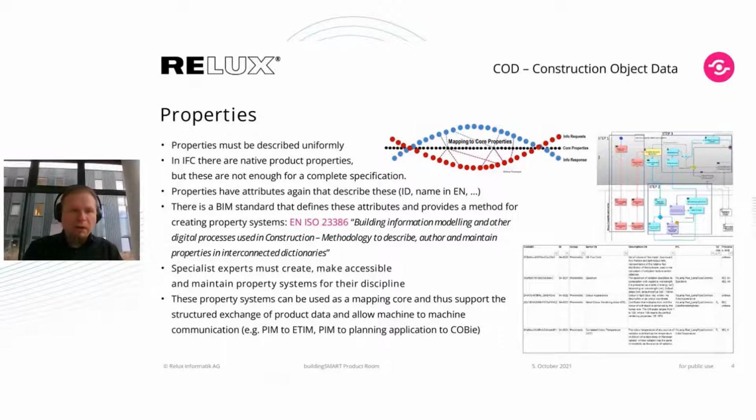This is also the same story. As I said, in IFC, you have for luminaires 48 properties, but the luminaire industry itself has about 500-something properties identified and also standardized on the ISO side to describe their products. And this is also across all the industries. Everybody has more properties of this product than you find natively in IFC, which is okay. This is normal because you cannot put everything in an IFC. This is close to impossible. Then it will explode. So many properties and so many objects you can transport.